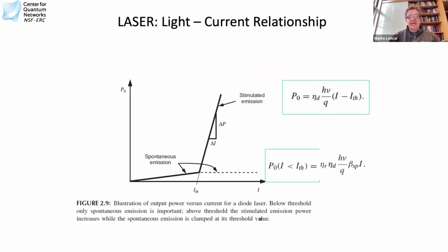When everything is said and done, this is a typical laser curve where you are injecting some current to excite the carriers. You keep injecting current, and most of the time nothing happens. Then at some point, you inject enough current, the process of stimulated emission takes over, and the laser starts emitting. You get this really nice sharp turn-on of the laser light. So this is a one-minute summary of how that works.